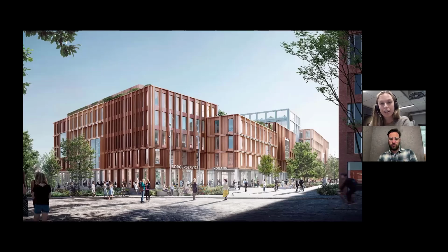So first one, this is a wood hub. It's a building in Denmark, or actually it's a whole block of buildings. And in this, the FEM-Design Grasshopper plugin was used to handle data transfer between different FEM-Design models, because this is a huge structure, and it was divided into, I think, 5 or 6 different FEM-Design models, one for each building and also one for a large basement, which is placed underneath here. And the API was really useful for efficiently moving loads and data around between those models.